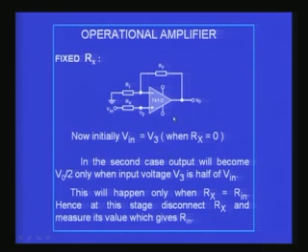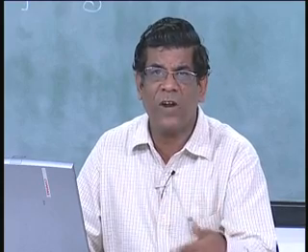From these two measurements, you can trim the value of Rx by introducing different higher values of fixed resistors till you get half of the previous value. Instead of directly using a potentiometer, you keep trying different values of resistors, increasing them in value till you get very close to half. But in principle, you will not be able to get a precise value of fixed resistors to get the exact value of the input resistance.